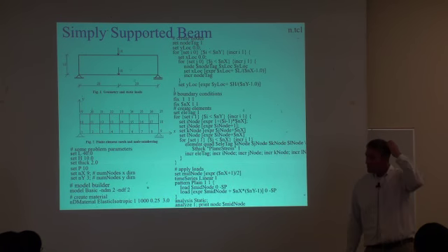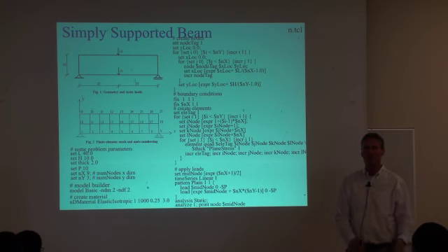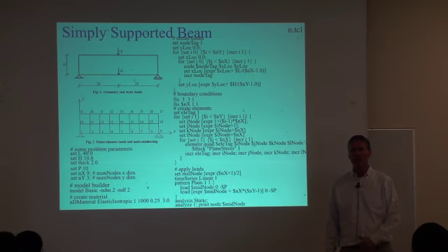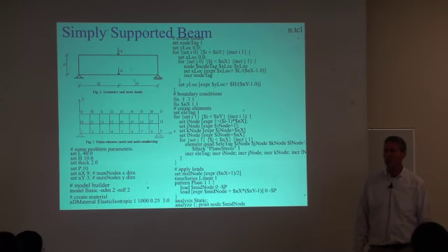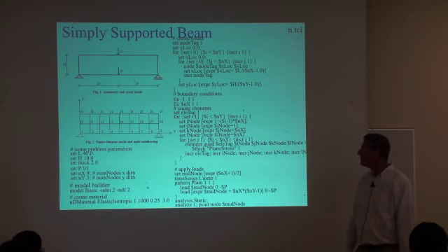Okay, so I'm going to change a little bit. OpenSees is not just about beam columns, the line elements, the beams, the trusses, the zero length elements. You've also got continuum elements in here. We're going to hear a great deal about these tomorrow. Professor Arduino is talking about the geotechnical parts of OpenSees. So I'm just going to, again, show you from the elastic point of view. So here we're going to model this beam. We're going to use quadrilateral elements.